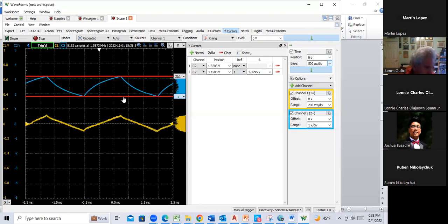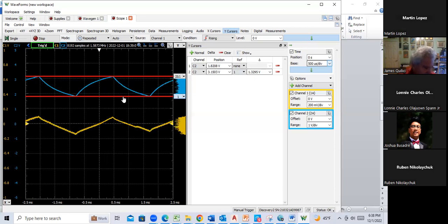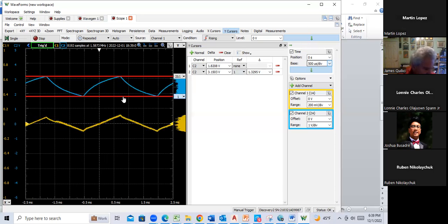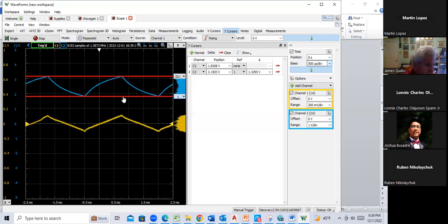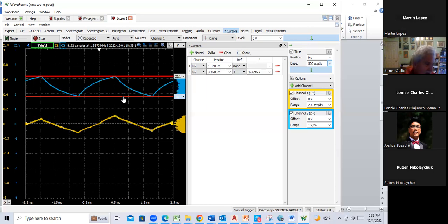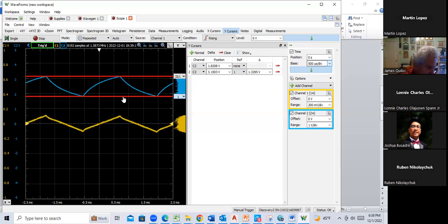I would compare the collector voltage, the base voltage, and the collector current to what you simulated in SPICE. So at the end, make a table, show what gain you got in SPICE, show what voltage peak to peak you got in SPICE, or list that in the table, and then comment on the DC parameters.